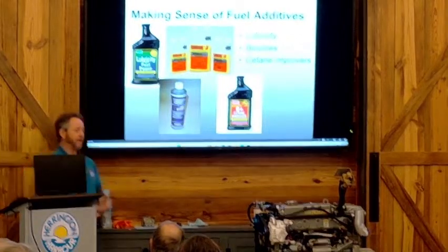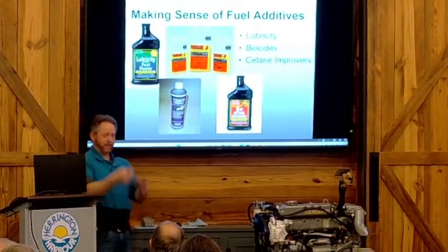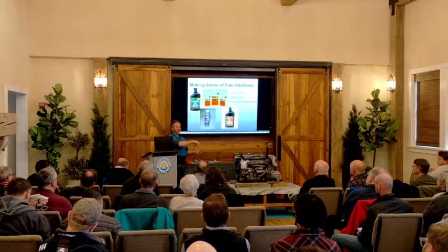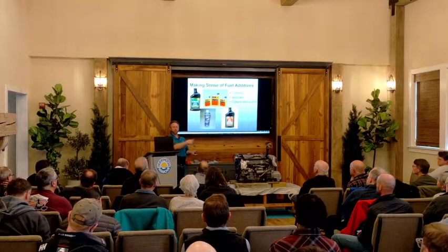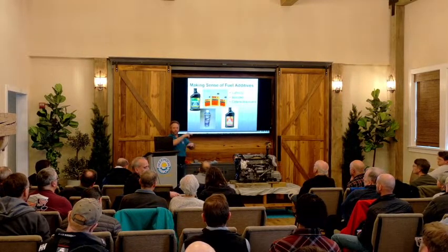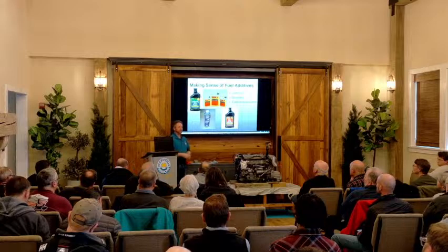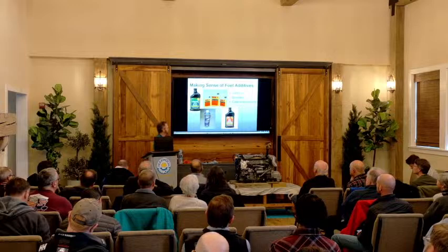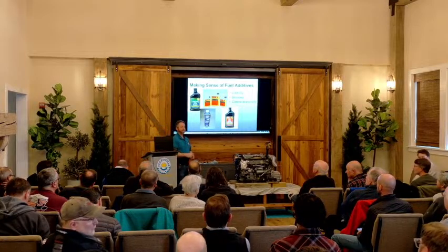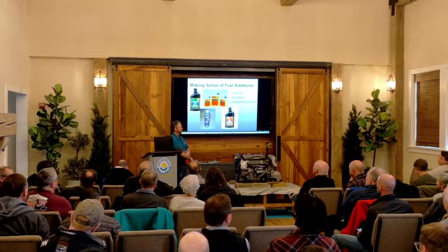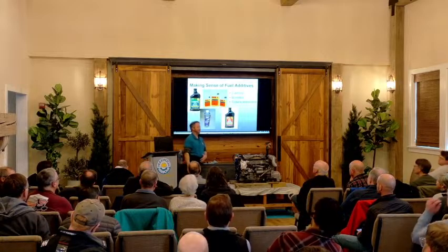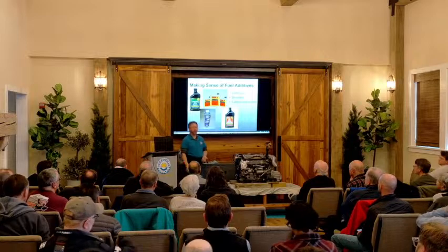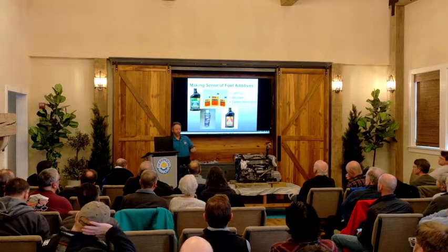And some companies may come out and take a fuel sample and see what the chemistry of the fuel is, and then they may put a cocktail into the fuel a couple weeks before they come out to allow it to get into the fuel and break down any of the microbes, et cetera, before they actually start polishing. So it's like dialysis for your fuel tank. Yes. Pretty much, yes.